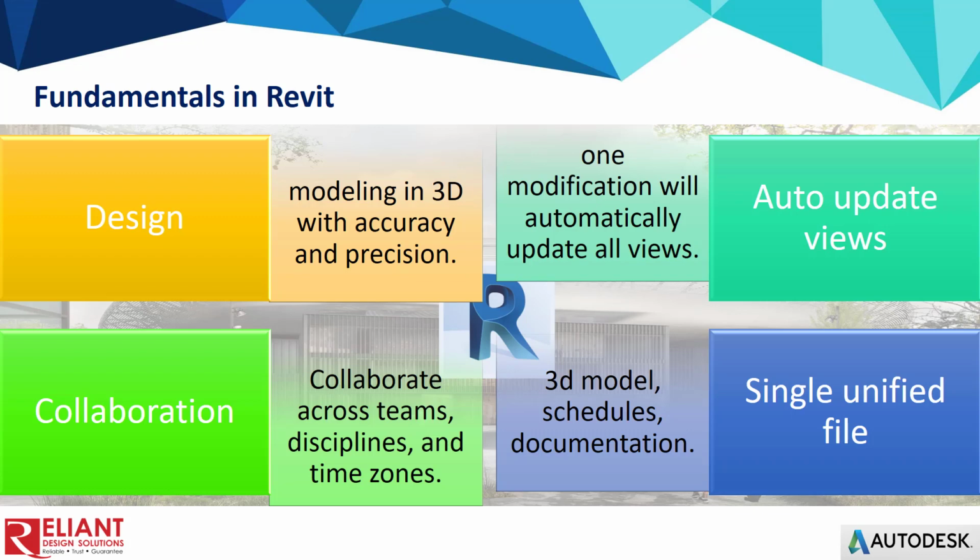So when there is a modification to the block, then they need to check each view of the drawing inside AutoCAD, and manually change it to the latest design or to the latest sizes. But with Revit software, each time you change the model or element in one view, the changes can be seen in all other views, as long as the model is in that particular view range.